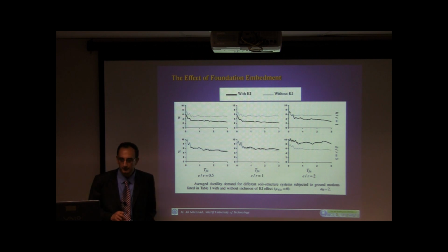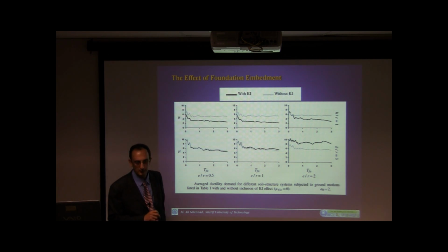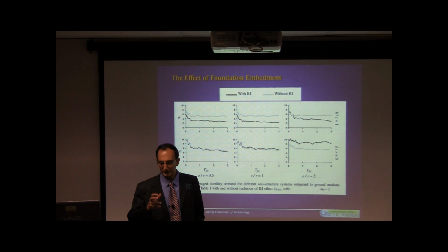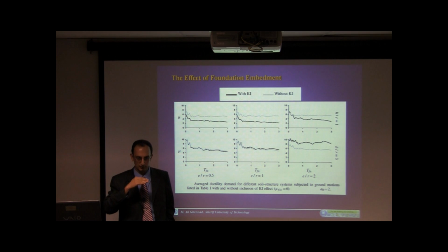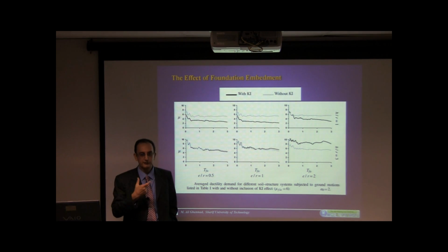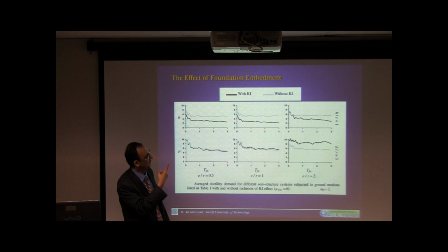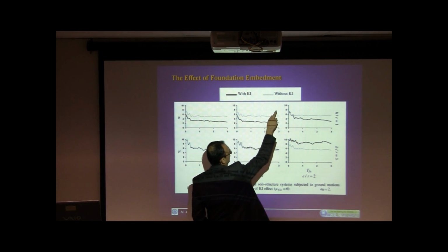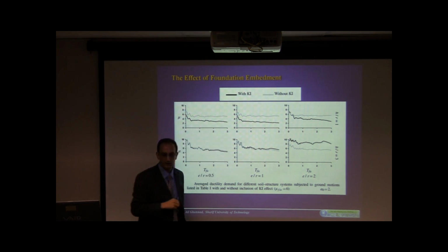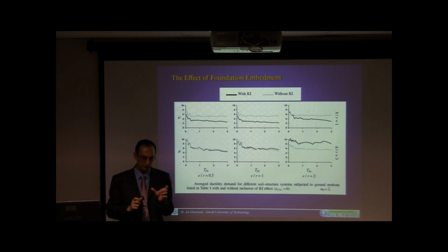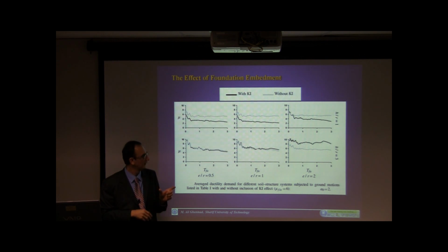Okay, sure. The free field is just horizontal, or it's also point rotation? The input motion, you mean? Yes. When I say without KI, it means just horizontal, or driving motion, and free field motion. But when we talk about the without kinematic interaction effect, it means just horizontal and free field motion. But when we say with KI, it means both. The resulted sway, it means the reduced one, filtered, and also the resulted rocking motion.